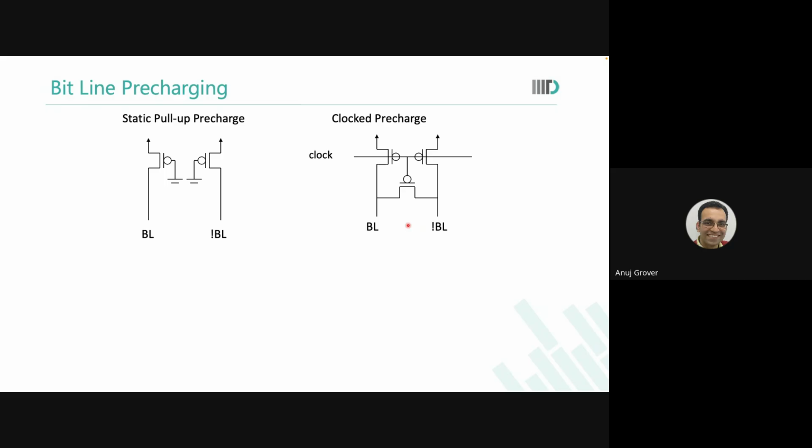Little by little, over multiple cycles, I would be losing 1 millivolt, 0.5 millivolt. After 100 cycles, I might have lost 10 millivolts, 15 millivolts, 20 millivolts. We don't know. Because we are continuously reading, giving some fixed amount of time to precharge the bit lines. And incidentally, on one particular bit line, I'm continuously reading a 0. So what happens?